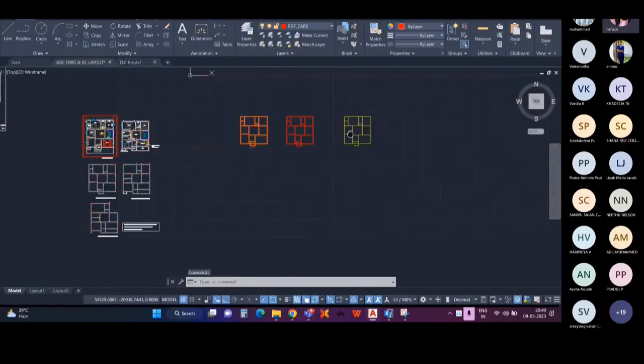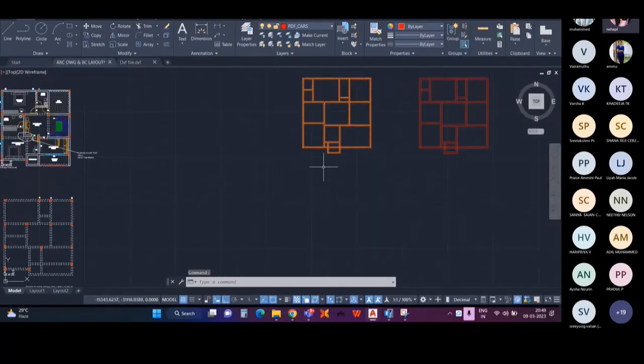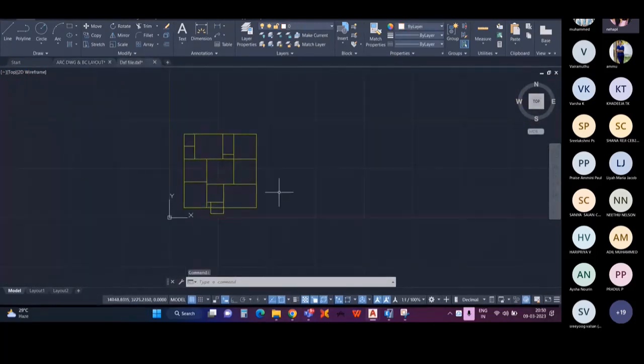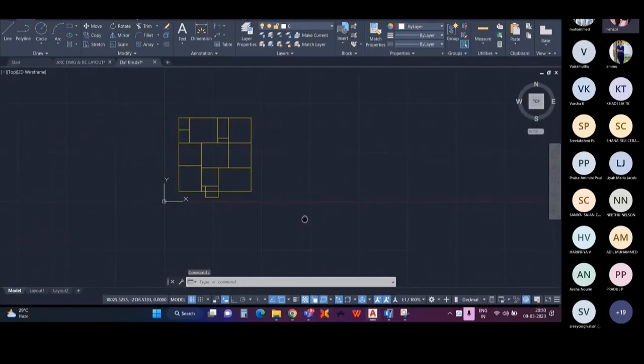First, I have drawn the central line of this beam using the multi-line command. After that, I have extracted the central line alone. After that, I have done both corrections. And after that, I just copied it to a new drawing file and then saved it as a DXF file. So that's the step to convert a drawing file to a DXF file.